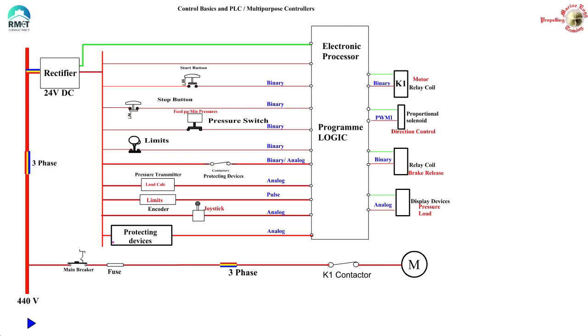So you see that the complexity has become unmanageable. If these complexities need to be executed with relays, it may make it very expensive, unreliable because of too many physical moving devices. Circuitry will get very complicated, too much of wiring, etc. So here we see that all the inputs are received by the multipurpose card where the logic gets processed, and the outputs also originate from the multipurpose card for control of various output devices.